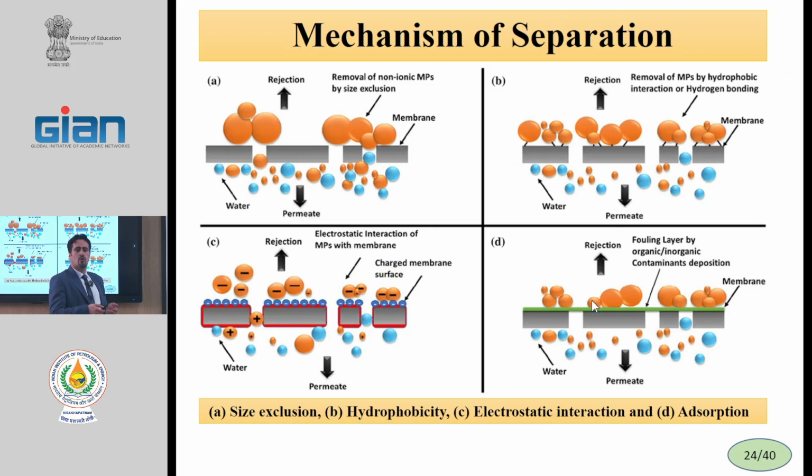But the adsorption capacity can be exhausted after a certain time, and this membrane is usually used for low concentrations of the feed or for short times. Usually adsorption membranes are used one time, for example in silica filters, for separation of one special molecule from the liquid.